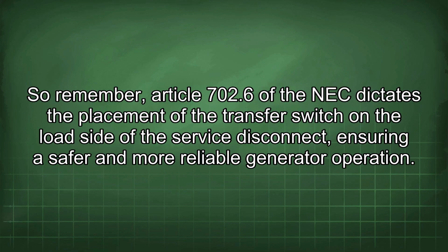So remember, Article 702.6 of the NEC dictates the placement of the transfer switch on the load side of the service disconnect, ensuring a safer and more reliable generator operation.